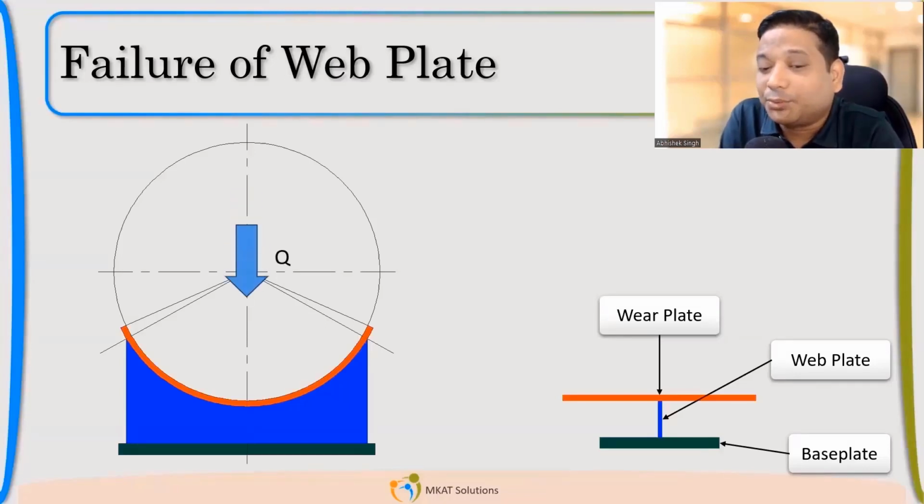If we talk about this Q, whether it is only the weight of the vessel or anything else also acting on it. Liquid weight, yes. Wind or seismic, no? So there will be a factor of wind and seismic, either of which will have a vertical component. So we find Q with that. There is a factor of wind or seismic, whatever is governing. So that is the vertical load.